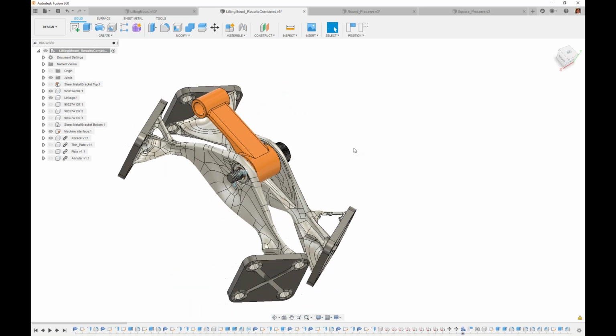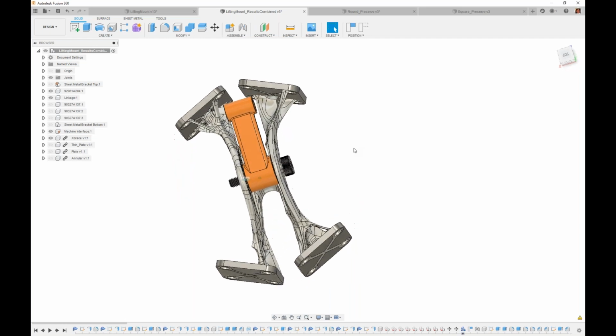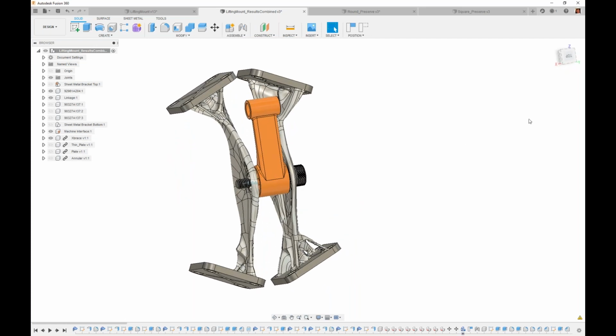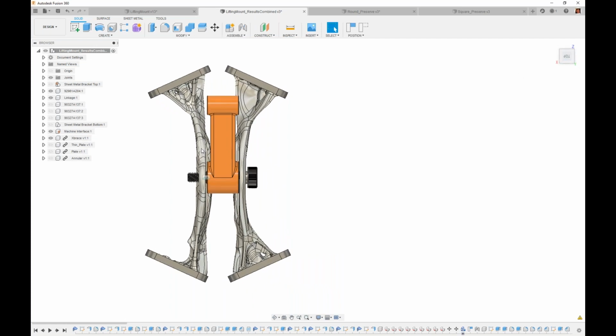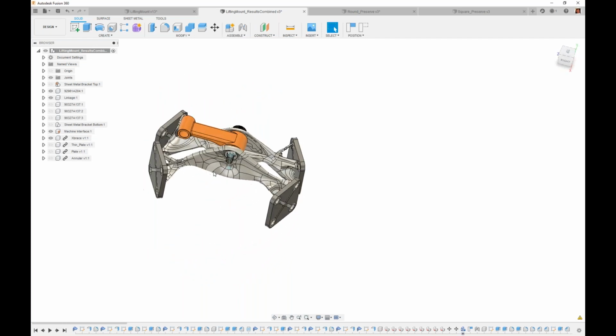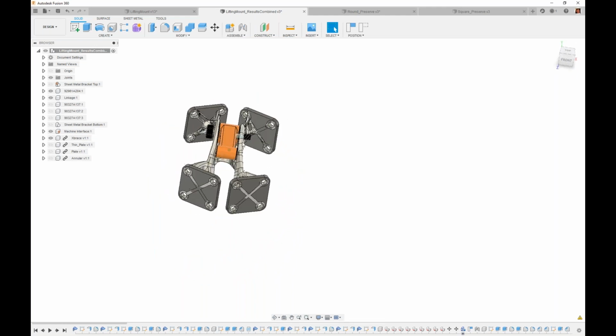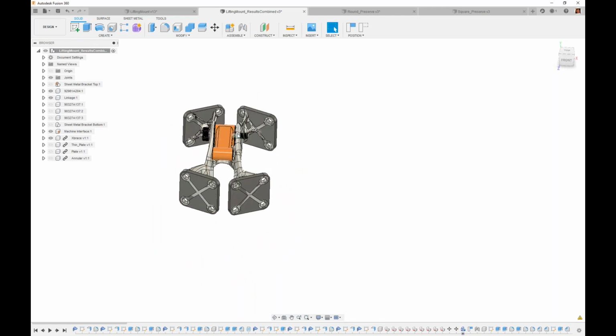There's a couple questions on symmetry next. The lever bracket. Why is this one not symmetric? At face value, it does look symmetric, but this geometry actually isn't. If you look at where the bracket lies, left to right, the mounting face for this attachment point is right along the center line, whereas these are not. So inherently, this geometry is not symmetric about the YZ plane or along the x-axis in this direction.